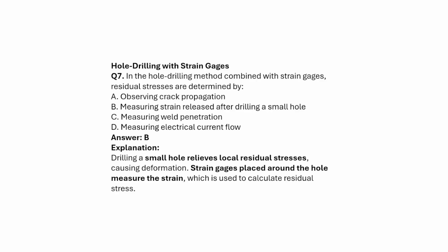Okay, drilling of the small hole relieves the localized residual stresses and causes the deformation. The strain gauge placed around the hole measures the strain, which is used to calculate the residual stresses.